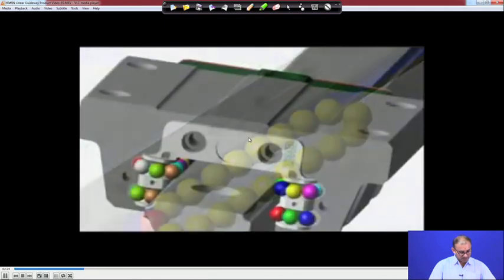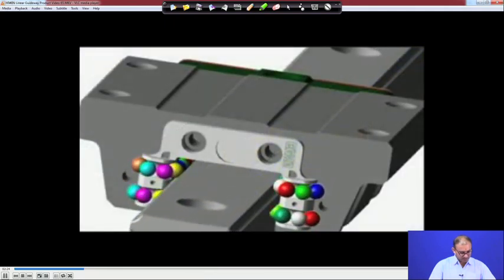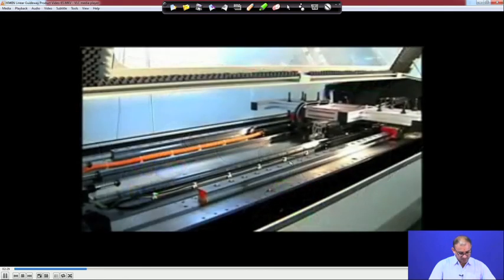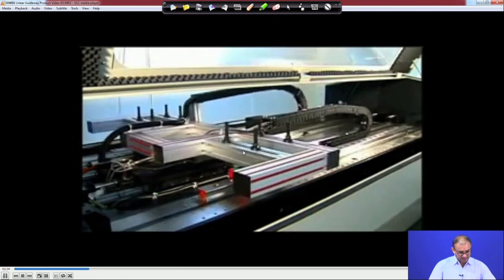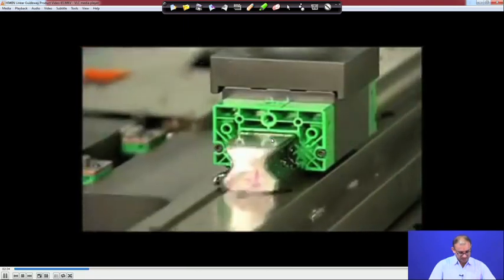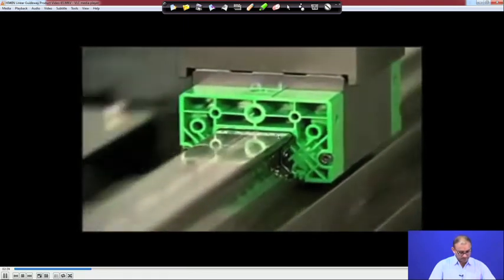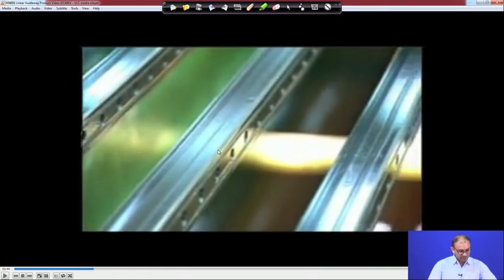And we have seen that if contact is at a ball point, there is no issue related to friction, very little friction is there. So, these are the number of balls which can be used, and these are the applications by which you can get things done. These are the sockets from where you can get this. Another advantage is that you are using a box type of structure. So, stiffness is very, very high in this case, because whatever other cross-section you are using, like a circular one, stiffness is less, but here it is a box type and a structured thing. That means it has different types of ribs. So, your stiffness will be very, very high in terms of straightness and load carrying capacity.